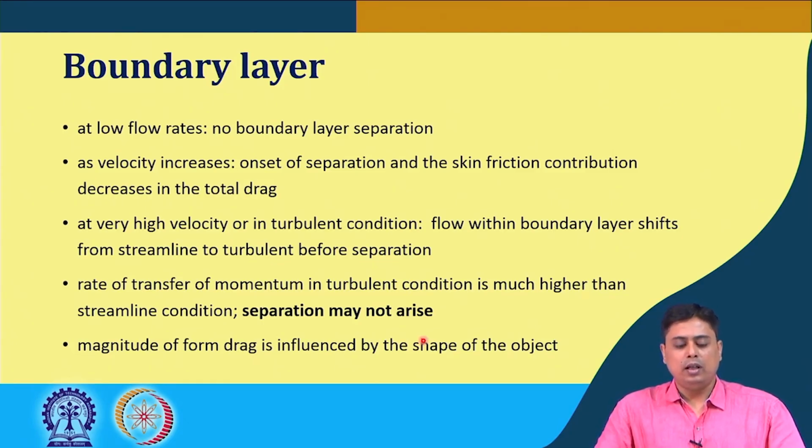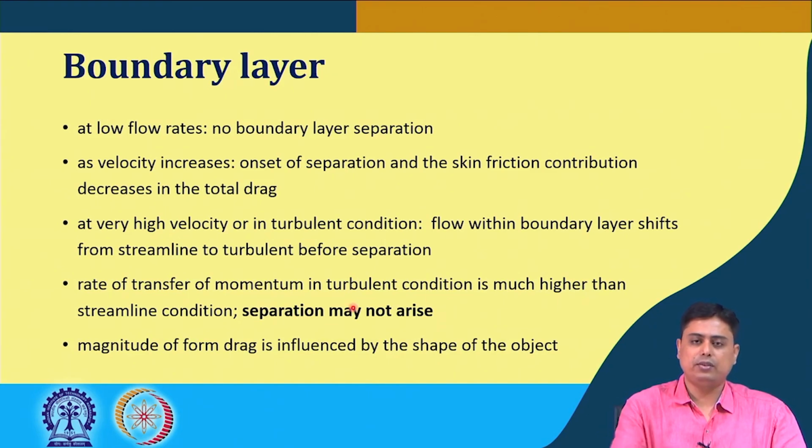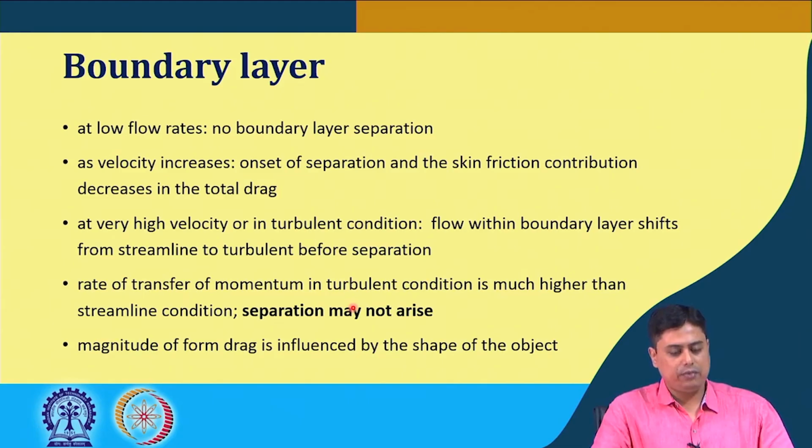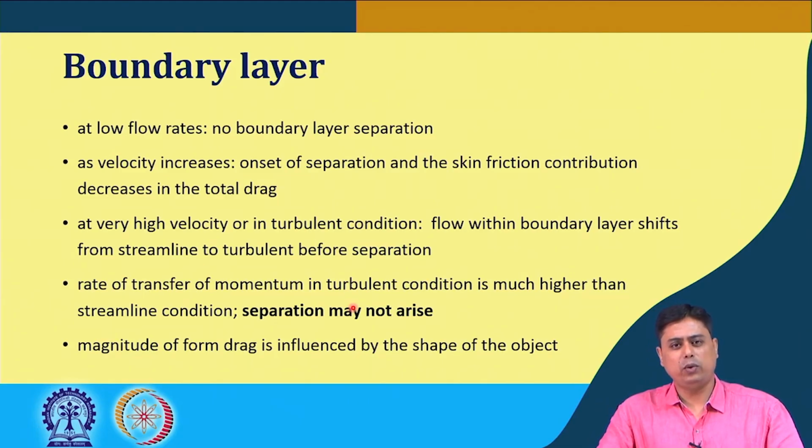Okay. Now, this is an interesting feature: in the laminar case, that is why we required sufficient length to have the fully developed flow. But in highly turbulent cases, since the boundary layer separation is suppressed by the high rate of transfer of momentum from one point to another, that fully developed length can be achieved quickly.